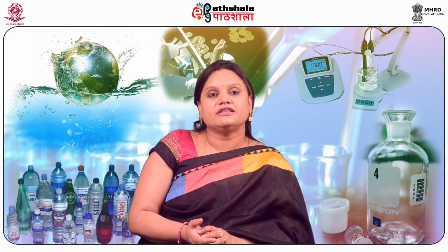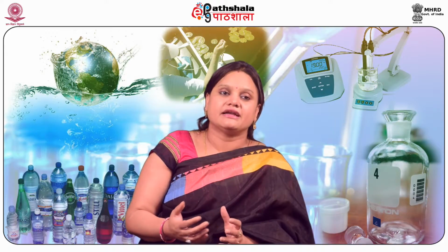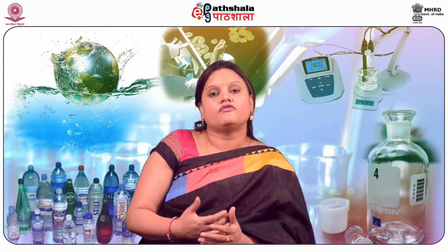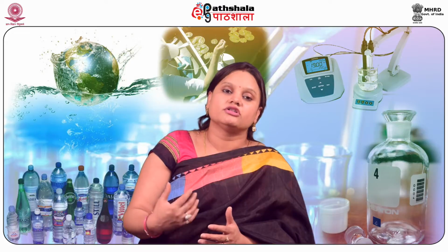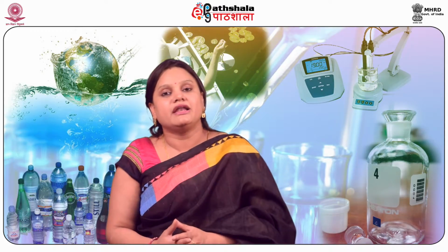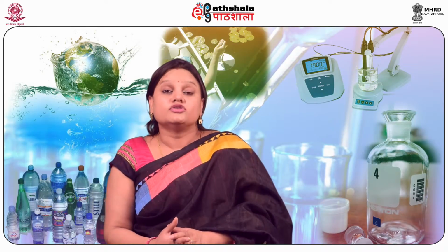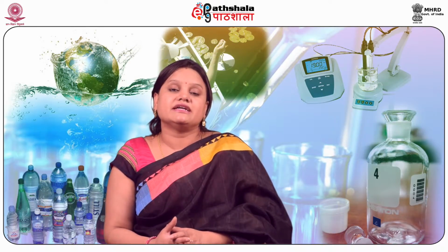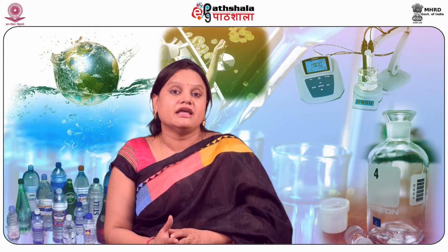But composite sampling is the way of sampling where we collect 4-5 samples in a time interval of either 12 hours or 24 hours, and then we mix all the samples and make a homogeneous sample, so that this sample is representative of the whole water body.